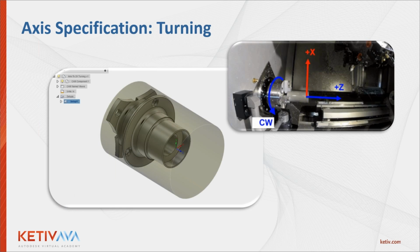So now on the turning operations, what do we have? We have the Z-axis going through the center of the part. This is going to be important, so you want to make sure that you have this work coordinate orientation. Otherwise, you're not going to get the correct toolpaths. When you bring in your tool and start creating the toolpaths, you're going to see that the tool may be in the wrong orientation. It might be milling from a different side or creating the toolpaths from a different side. So this is the orientation that you want to follow when you are doing turning operations.